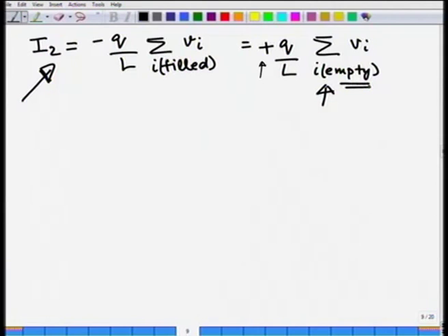In that case, I define this hypothetical particle. So, if I carry out the summation over empty states, if I think of them as hypothetical particles occupying the empty states, in such cases like band 2, I can define a quantity called holes, which have now positive charge and also mass, which is effective mass, which is positive in this case.